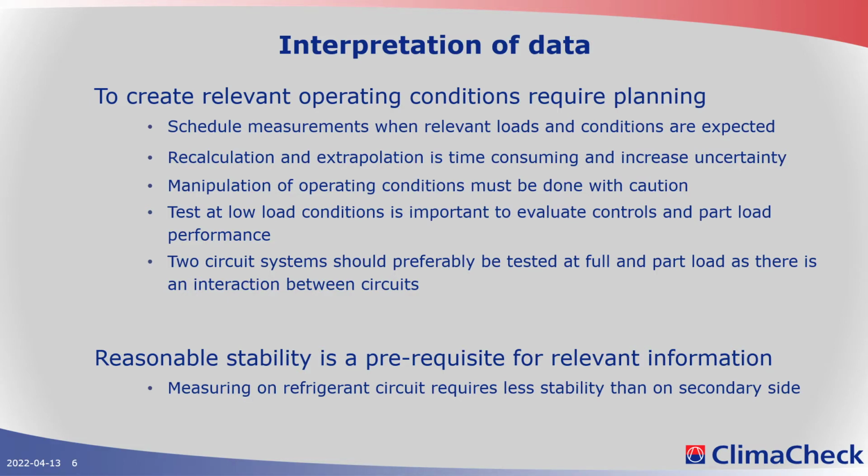Unless you have stable operation, you cannot check that your compressor is okay, you cannot check that your refrigerant charge is okay, you cannot check that your expansion valve works. So it's a meaningless test to run a compressor at continuously varying conditions. You need to plan to have reasonable stability of the load.